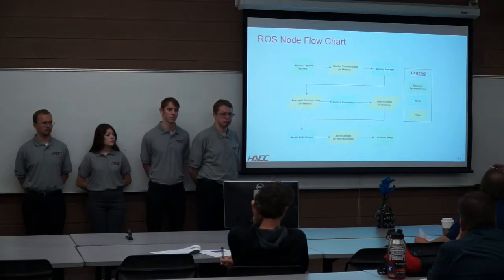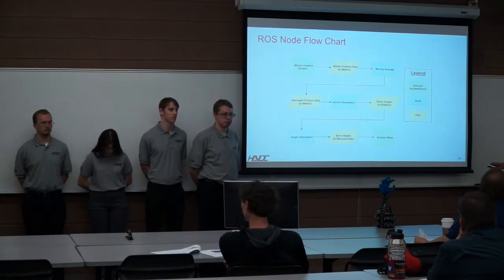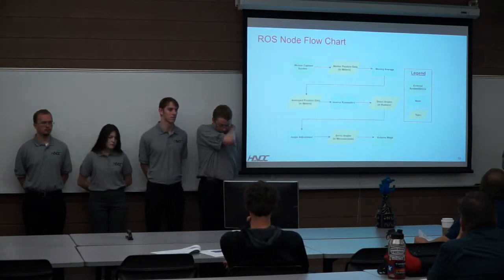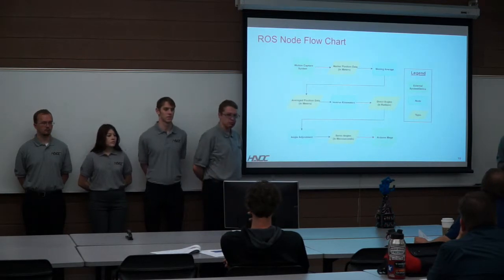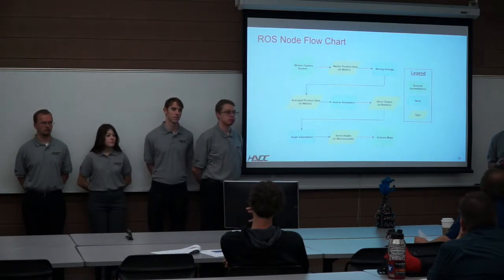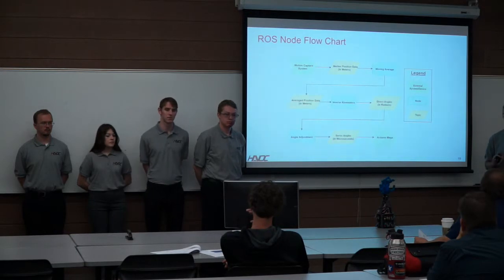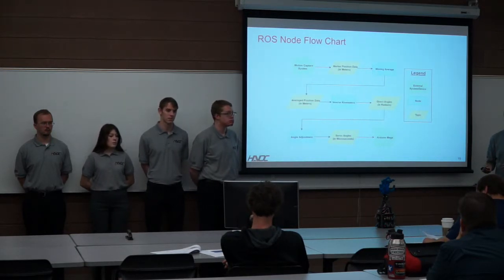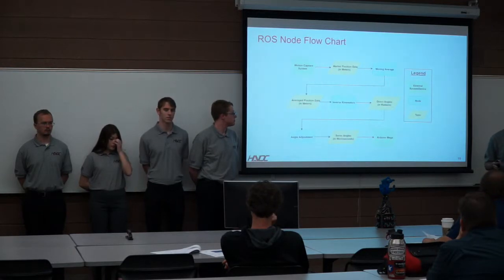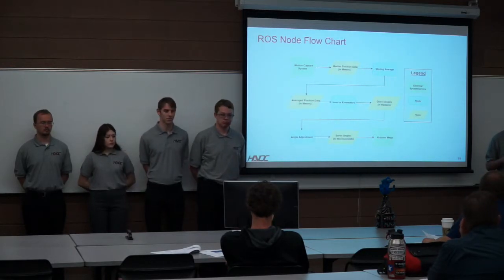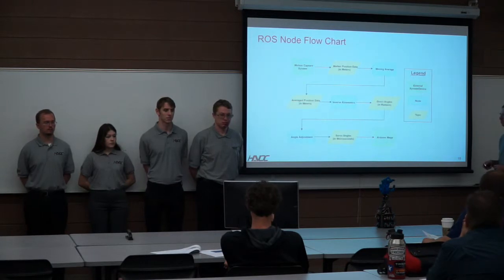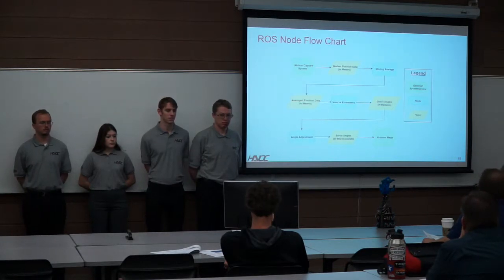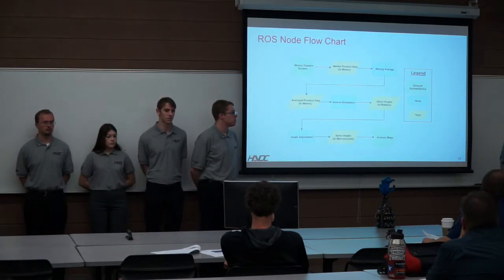We then send those to an angle adjustment that will output the values in microseconds. The Arduino is controlling our servos based on the microsecond value, because this allows for a greater range and accuracy over the standard servo write function in the Arduino. We then send this to the Arduino Mega and update our servos with our angles.